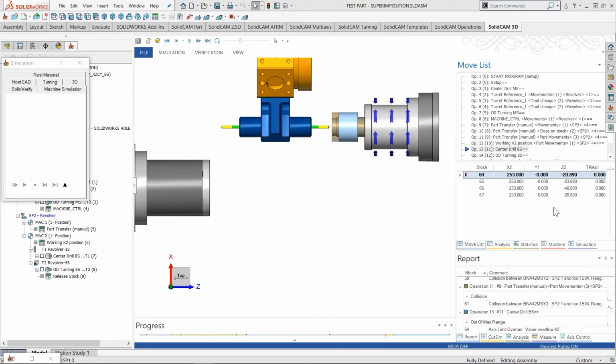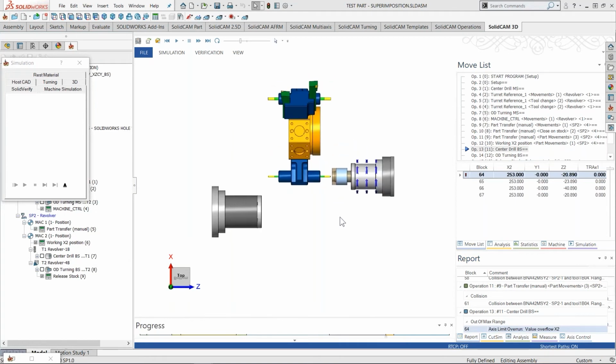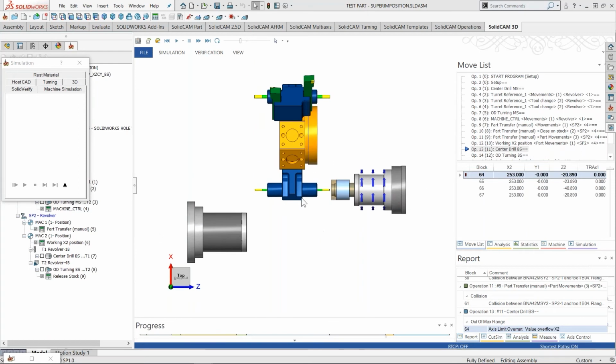Okay, this is now interesting because what we said there is that X2 and Z2 is my kinematic axis. So it means that X2 and Z2 will be moved towards the tooltip. In this case, I should probably take the turret to some safety position down below, and then I will have this working completely fine. Otherwise, if I leave it as it is without the axis pattern, you will probably see my axis limit overflow here on X2. It's done. So I can click over here and it's there, yes? So guys, how can we actually activate the superimposition and run this together.